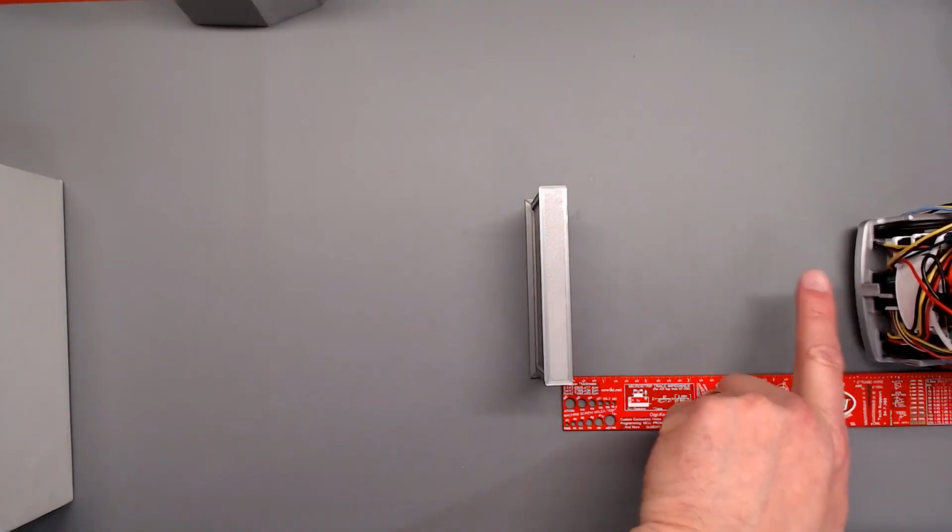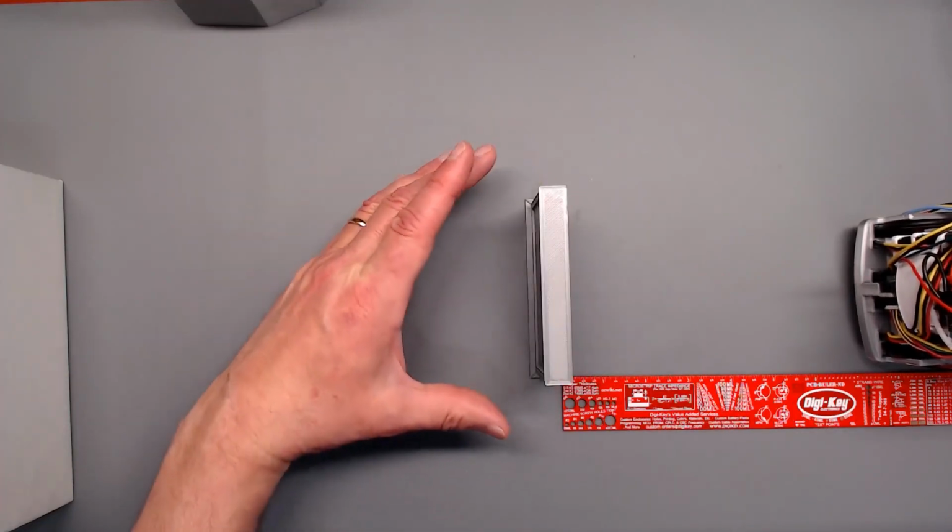Same thing for when I make the turn to pull into the driveway from the traffic lane. I can use the sensor to measure this distance so that I know how far to pull up and make sure that the sensor distance and my encoders are in correlation with each other, giving me greater repeatability, accuracy, and better localization at the destination points.